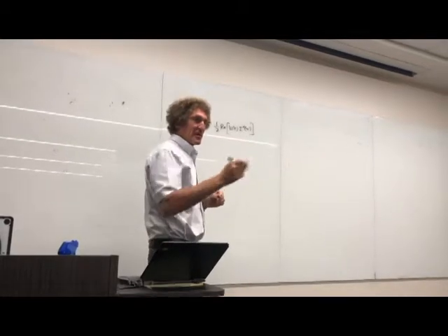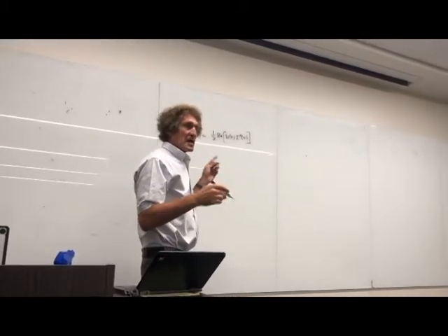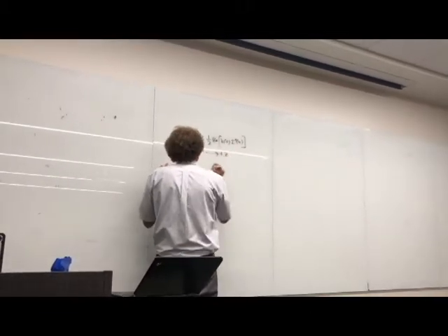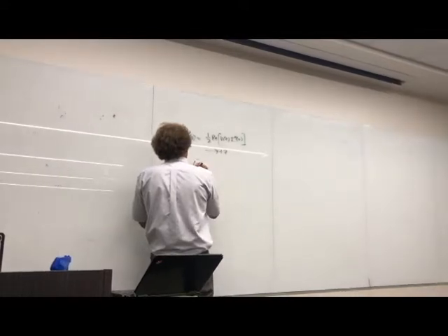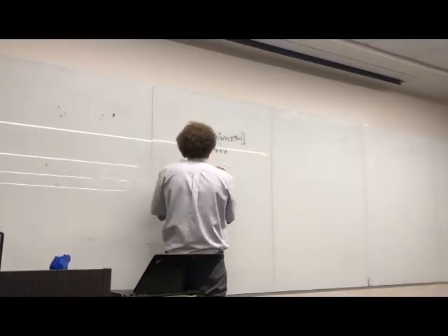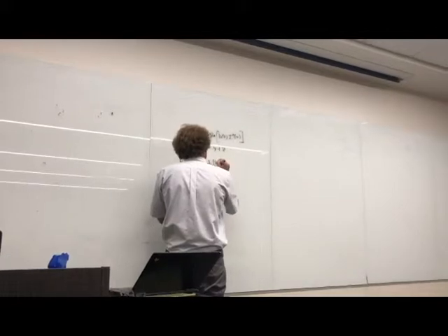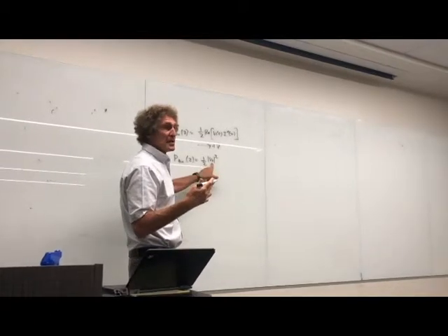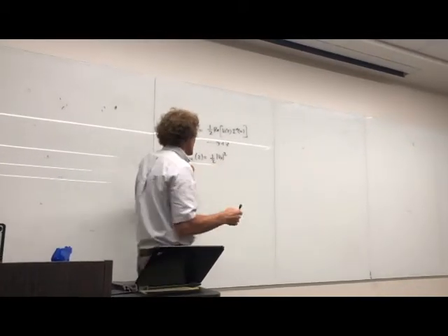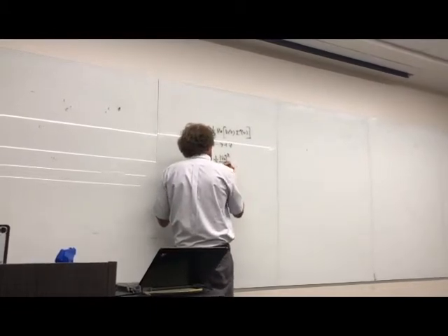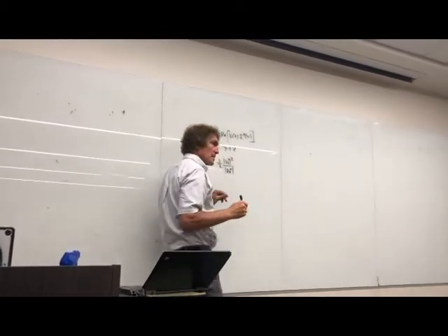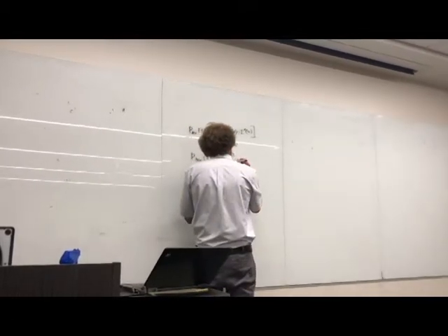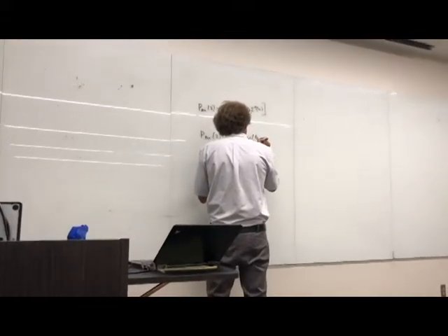Now, once I put in the equations for this, I said if we're just looking at power traveling in the plus Z direction, we found out that the average power flowing down the transmission line was actually 1/2 the magnitude of V naught squared. Now that's the voltage at the beginning of the transmission line. It's the applied voltage, and it's the magnitude, by the way. And it's divided by the magnitude of Z0 plus. Now remember, Z0 can have an imaginary part, but it's the magnitude. Then it's times the cosine of the phase angle of Z naught.